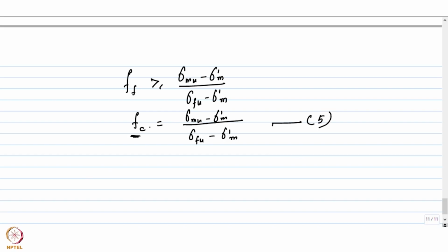And if the volume fraction of the fiber is small, then you can expect the fibers to break because their amount is too low to carry the load. So as you increase the load, the fibers will start to fracture, right?